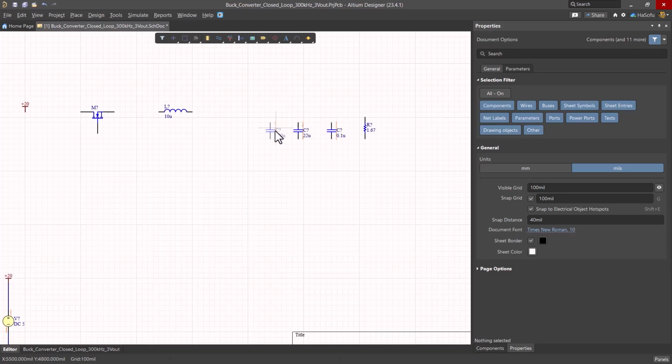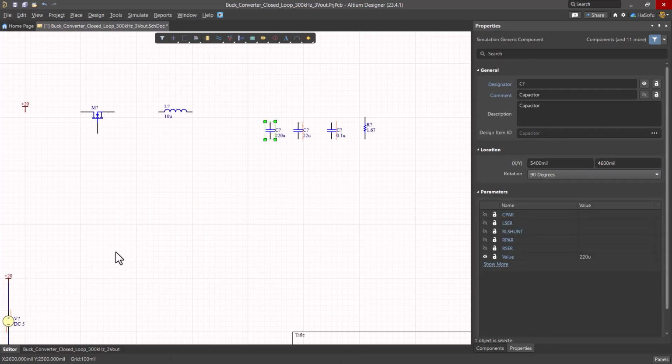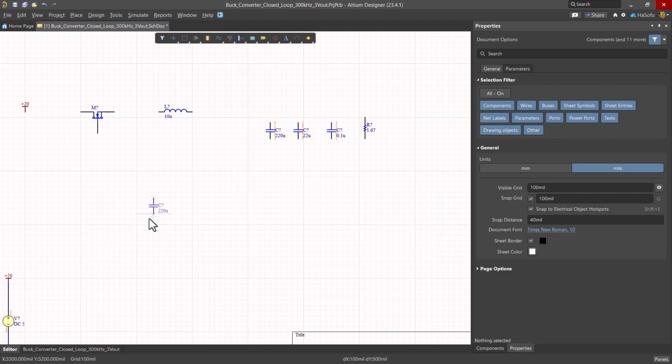Okay, adjust these devices. Okay, so now we need some more capacitors. I'm going to copy this capacitor with Control C, Control V to paste, and I can rotate that as I'm placing it. I'm doing the control loop here, so I'm going to paste. This is the compensator. Copy this resistor. So these three elements will make the compensator. I also need some other elements for my conditioning circuit, like a voltage divider on the output voltage from this circuit.